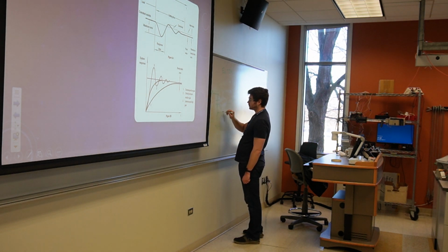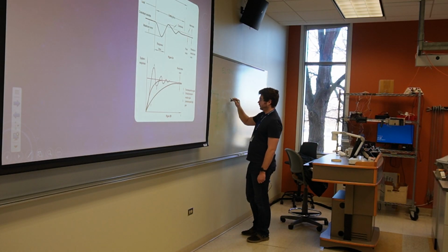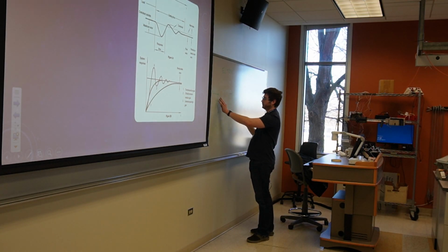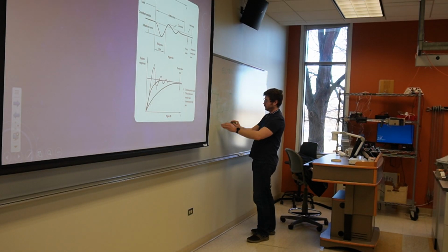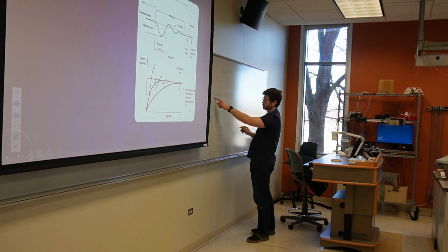The voltage at this point will change. So if we pulse it, without the capacitor and resistor, it'll look like this. It'll be a perfect square wave, right? Low to high to low. But with the capacitor and that resistor, it will charge quickly.